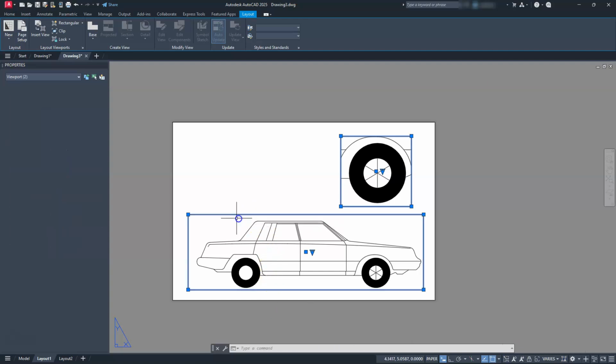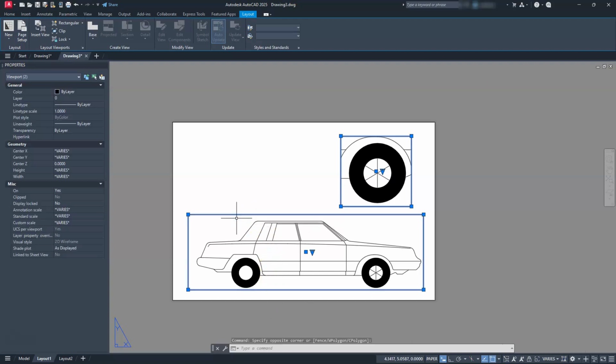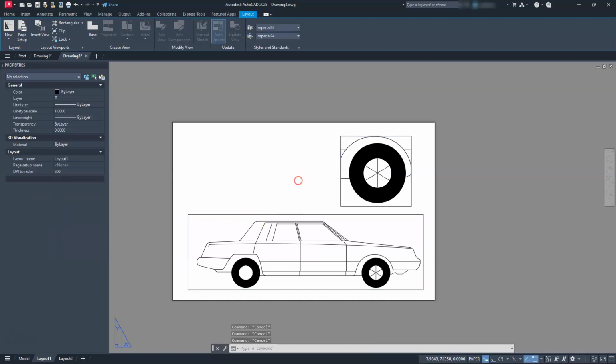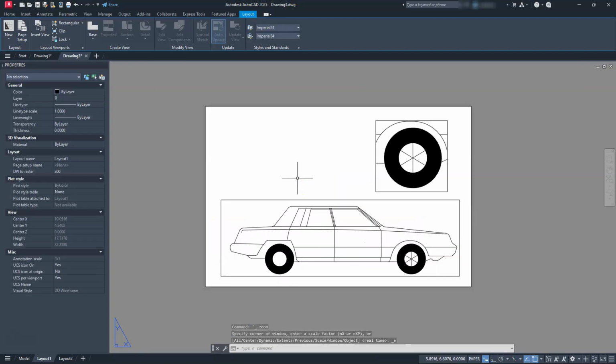But that should be kind of everything that you need to know, if you're dealing with scale factors versus paper sizes and things of that nature. Just to sum it up for you, all of this stuff is linked together, especially when you're doing any kind of drafting, because you need to know what size your scale is in order to make it fit onto the title block. If you can't calculate it, don't be afraid to use not to scale if it's something special.